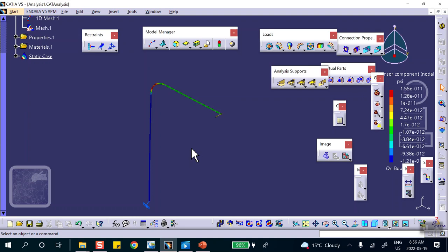But if you look at this problem, this plexiglass in front of me, these can be modeled as beams. This glass can be modeled as shell. You can do it with solid, but look at the thickness, half an inch, a third of an inch. Try to fill this thing with those elements. So people do it with shell, okay? And there is something complicated down at the bottom. Maybe some bulky object, and things like that, then you have to do solid. Together they have to work. Okay, any question about this?